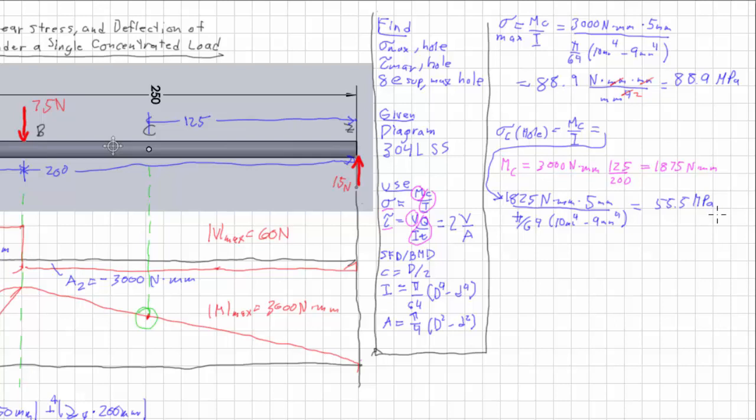So the actual stress is going to be higher than this, but we're not going to consider that stress concentration in this particular video. But it's good to know what it would normally be without the hole at that location, because that would be the first step in getting a more realistic answer. It's going to be much higher in that area once the hole is taken into consideration.